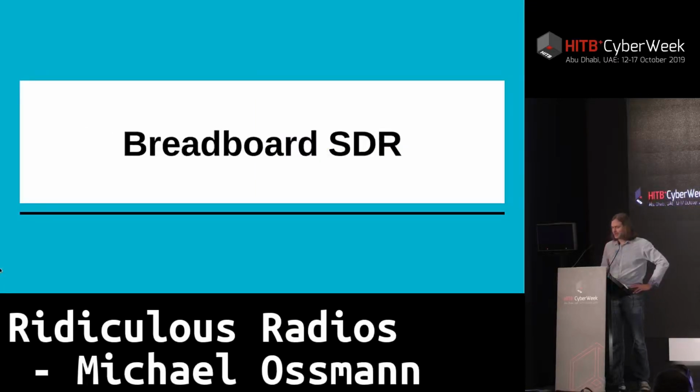And so what I came up with is a little circuit that I call my breadboard SDR. And I've had thoughts about making more breadboard SDR projects, but this is the first one. And it's the simplest radio receiver that I've been able to devise that uses a general purpose microcontroller and that can receive radio signals that are much higher frequency than the speed of the analog to digital converter. The analog to digital converter on a typical microcontroller only operates at a few 100,000 samples per second, or maybe a few million samples per second.